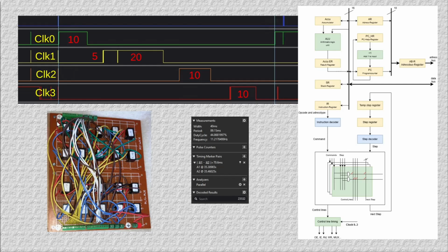If we want to send an input enable signal to a register, this module is responsible for sending a clear signal to this register during clock 0. In clock 1, we will send an input enable to all registers which should be written during this cycle.